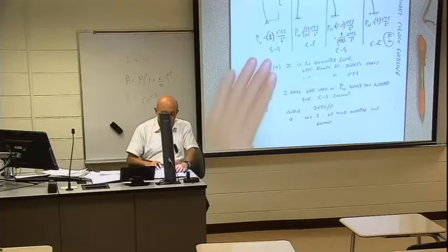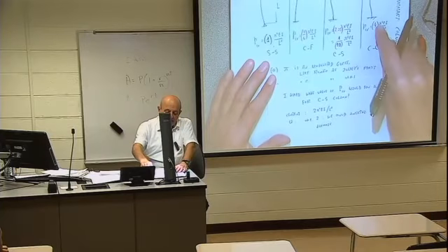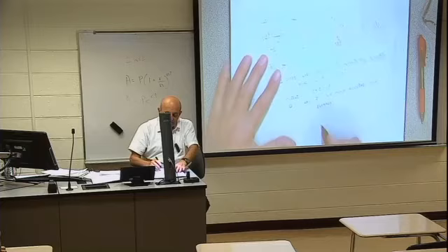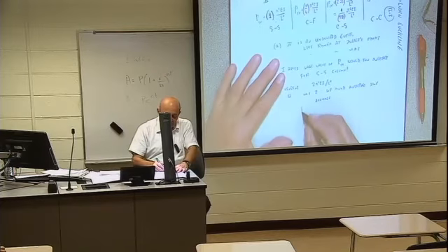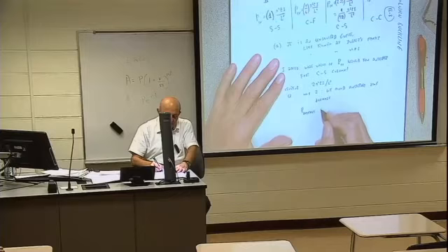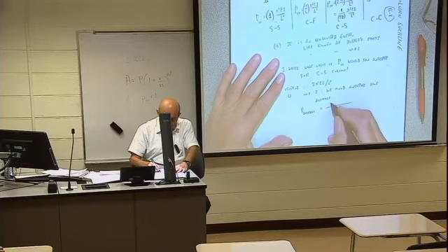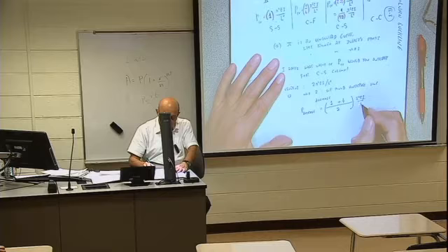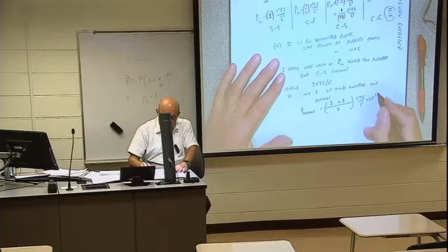Average would be, look, in clamped beam it is 4. In simply supported it is 1. So one could anticipate P average will be 1 plus 4 divided by 2 pi square EI over L square, which is 2.5 pi square EI over L square.